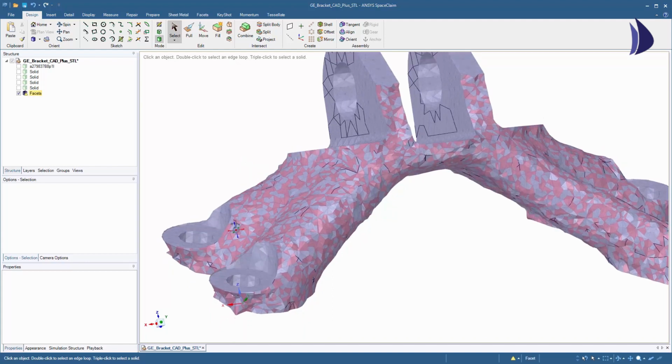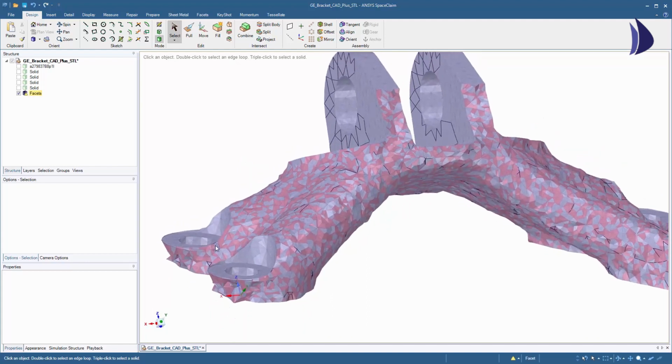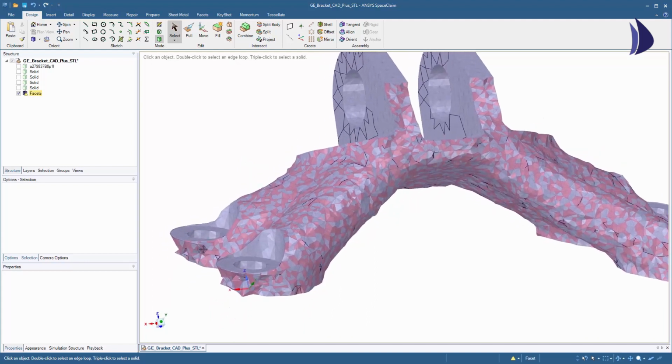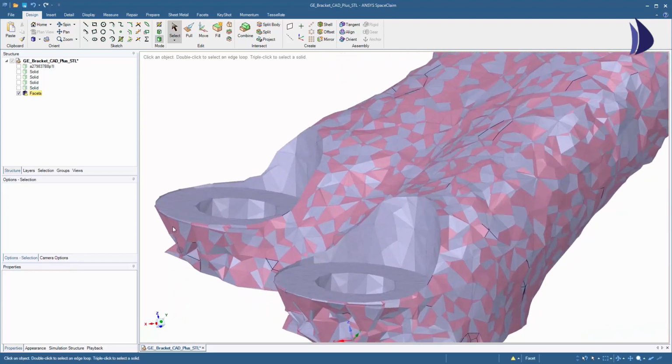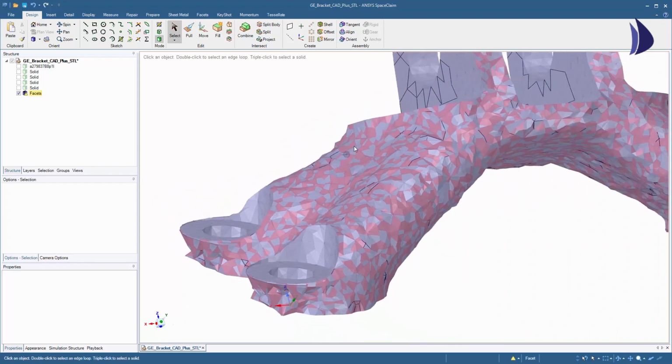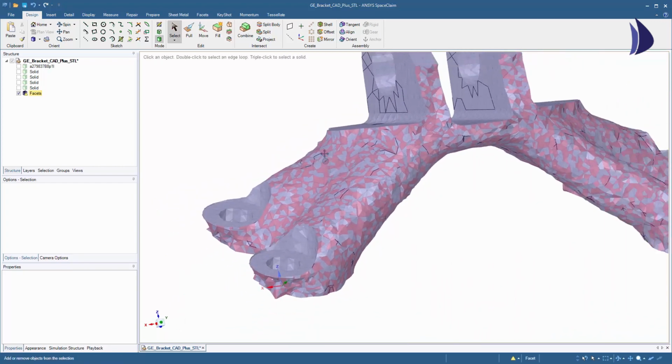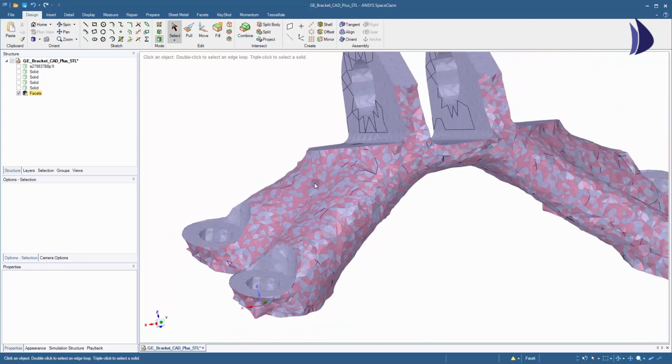As we take a look at this, you can see it's removed a lot of the extra geometry. But we might want to make further edits to the design to prep it for additive manufacturing. You'll notice it took away a lot of the geometry within the pads. We see that we might want to smooth some areas out. And also you'll notice some inconsistencies with the STL file. Some triangles are inverted and we have overconnected edges.